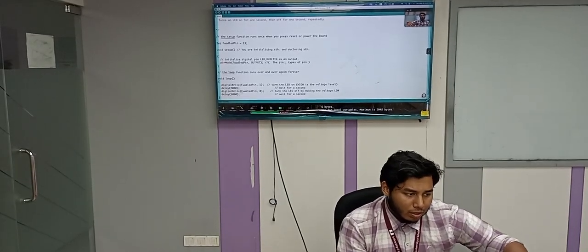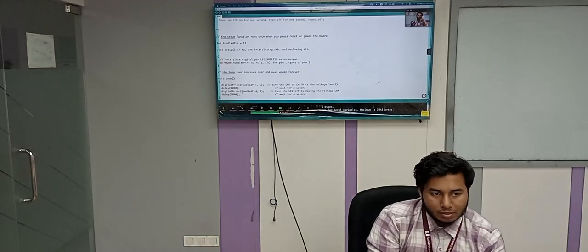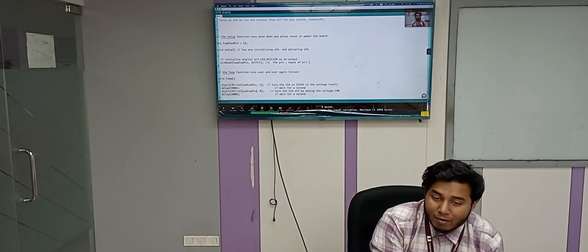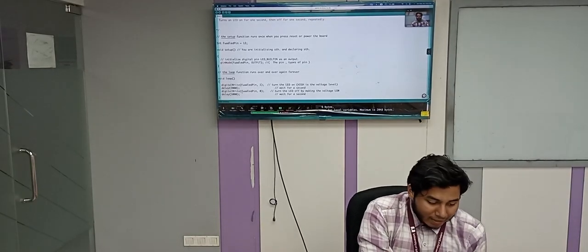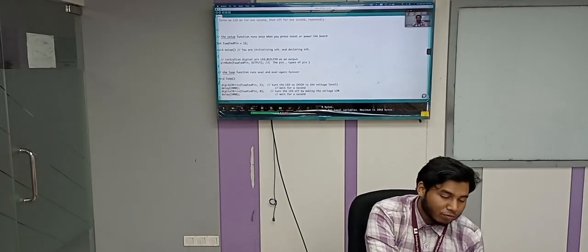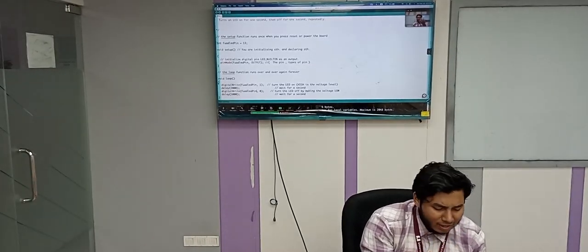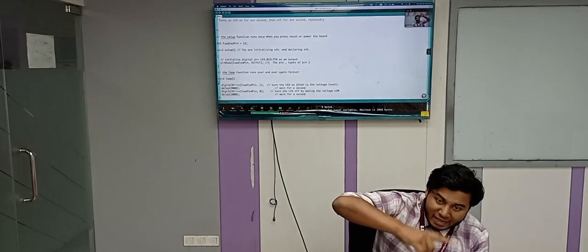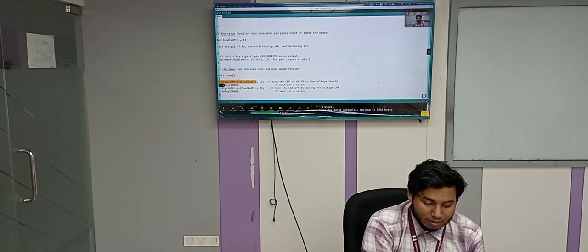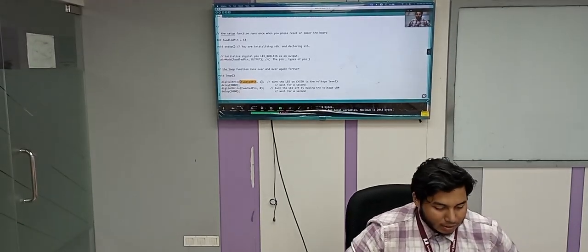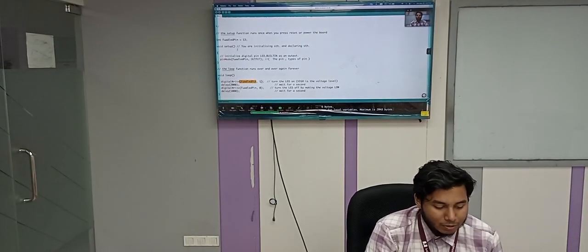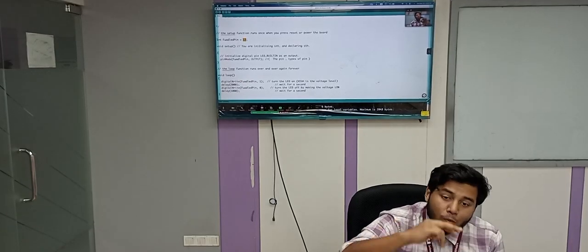Whenever you work on a bigger purpose, or on many lines, you have multiple integers, multiple variables. How are you going to declare them? You have to declare them with a name, because every time there are 13, 7, 4, 12, 11 or 10. Every time you would have to change that in every line. If you want to change the pin number from 7 to 9, you just change it at the top, above the word setup.